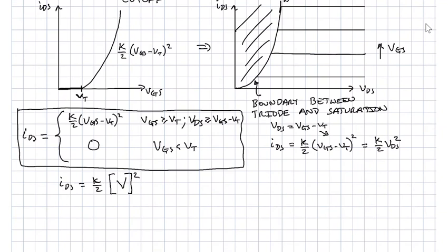What units does K have to have? We know IDS is amps. We'll say milliamps, just because amps is a big number, and for MOSFETs we'll usually be in the milliamp regime. The rest is unitless, it's constant. So our units for K have to be milliamps per volt squared to get things to work out.